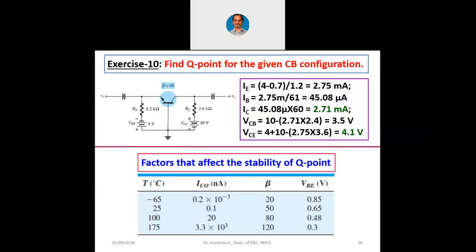Recall the basics which you have studied about the diode in either engineering physics or basic electronics, where for the diode you have studied an equation of the current. In the expression for the diode current, the reverse saturation current always comes into the picture. Reverse saturation current means the current that is flowing through the junction when the junction is reverse biased.